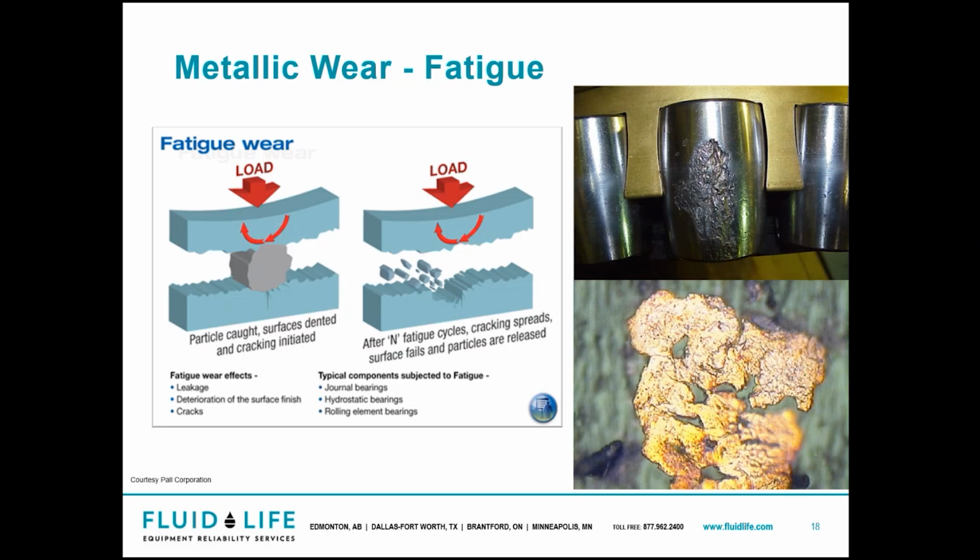Now, if something gets overloaded or you get a hard particle in there, it's going to cause plastic deformation. And plastic deformation means permanent rupture of the shape. So every time you go over that same spot, it's going to propagate a crack further and further until you have a stress concentration like you see in this graphic here, and it'll break off and cause little flakes in your oil. And that can actually cause more damage, right? Because now you have a hard particle in there that can propagate more fatigue cracks or cause abrasion or adhesion.